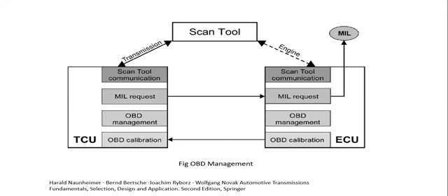In the US, the forerunner with respect to exhaust gas legislation for motor vehicles is CARB, the California Air Resources Board. In the case of California's LEV legislation, which covers low emission vehicles, there are no consistent threshold values for all new vehicles, such as in the case of European directives. Rather, there are different threshold values and their gradual implementation. Vehicle manufacturers are obligated to maintain an average fleet emission standard for all vehicles sold.